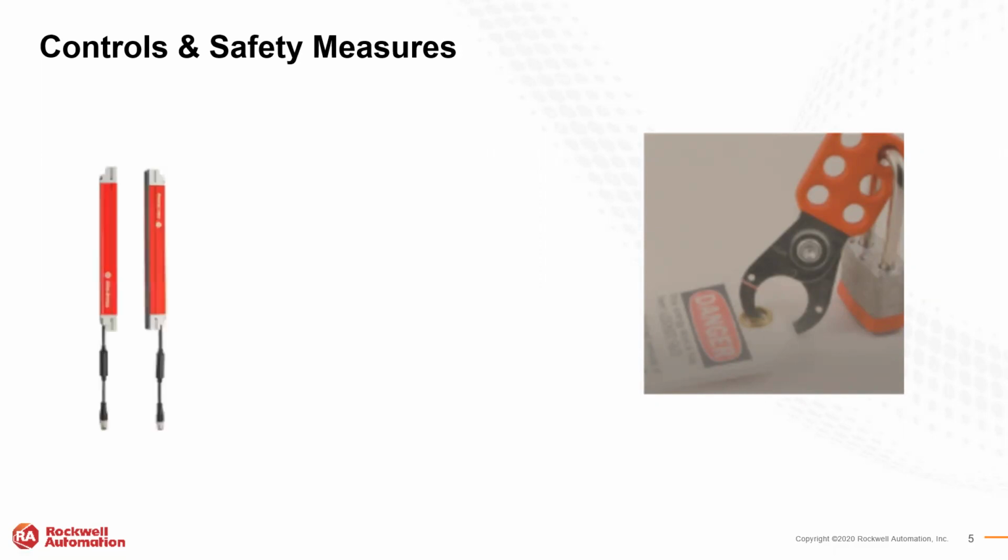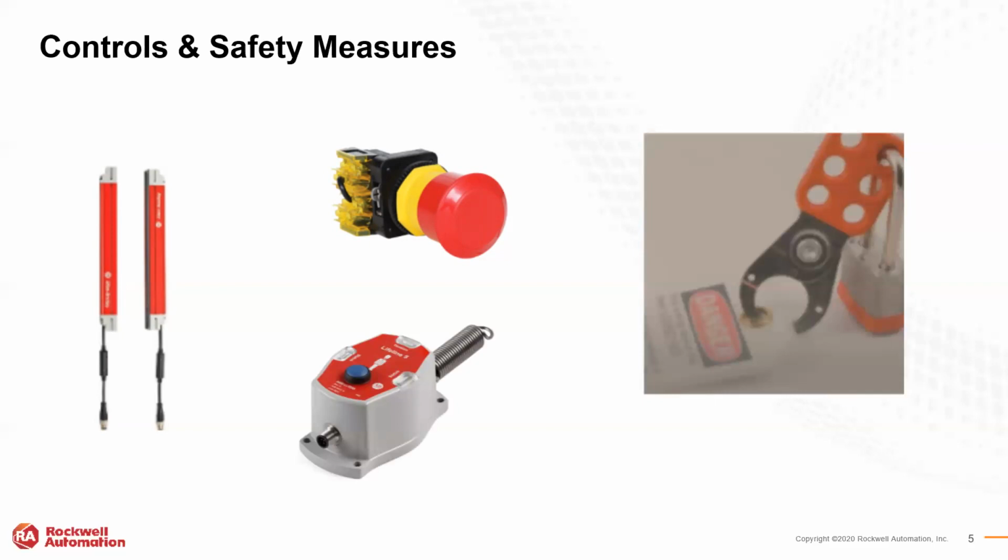The question is, can we carefully and with good engineering practices apply more modern guarding and controls techniques to minimize the use, to require the use of lockout, tagout in certain tasks? And then mixed together with this sometimes is the concept of emergency stop. So these are really three things we have to have for machinery: lockout, tagout, guarding, and emergency stop, including things like pull cords, which is really just a long emergency stop function interface. It's not really a safeguard by itself in any means, but an emergency stop implemented.